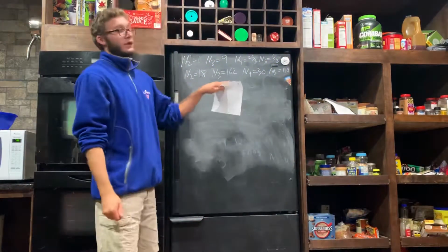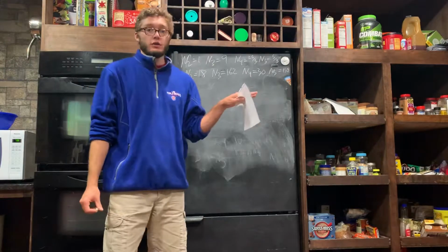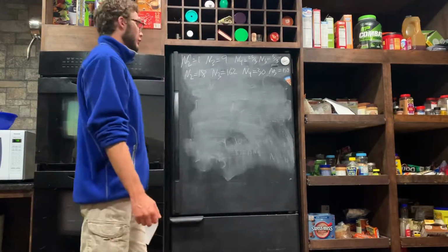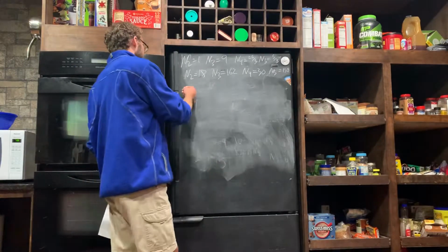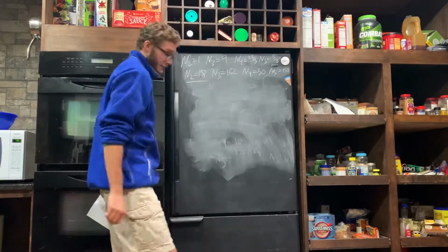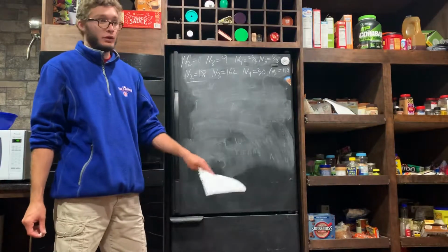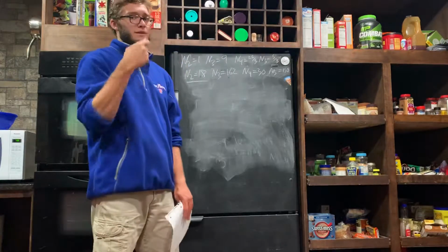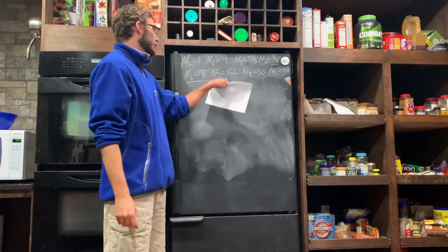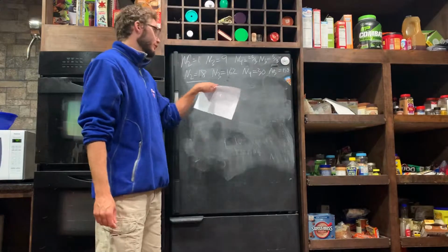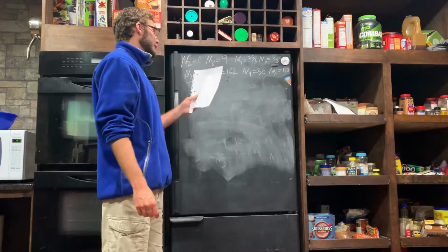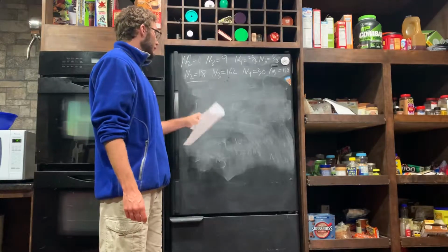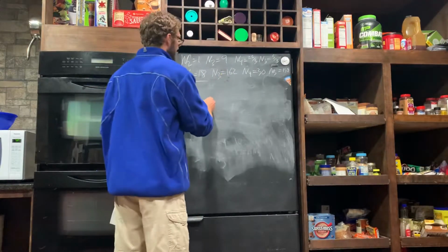If we look at the interference tables for a 20-degree pressure angle pinion gear, we see that we meet the minimum of 18, and we're under the max, which is going to be insanely high. I think for 17 it's 1,000 something, so for 18 it's got to be like 10,000 something. And there we go. We're going to plug this in.